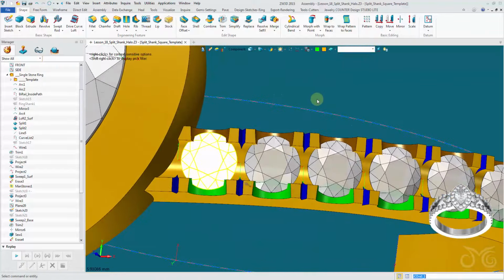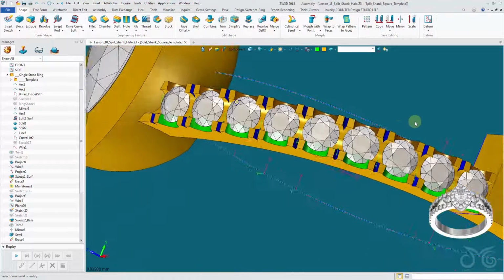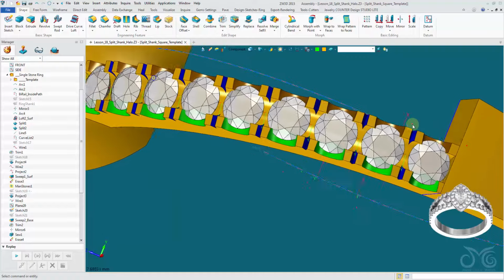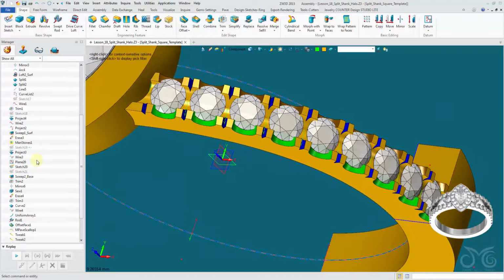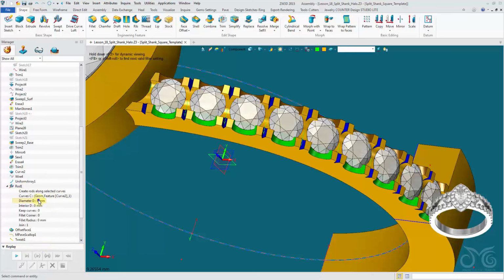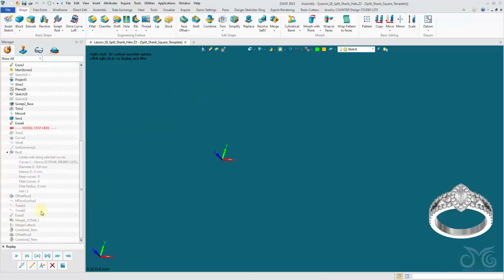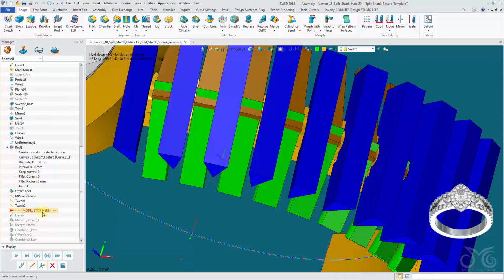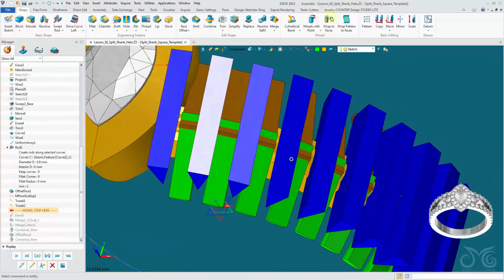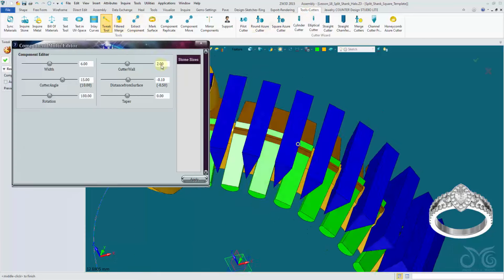Okay, so we don't have much material covering the stone here, so I may want to come in and modify my scallop a bit. First of all, I'm going to open up the rod. I'll drop the diameter of the rod down to a 0.9. We can delay the solve, that's fine. I'm going to come after the tweaks. I'm going to tweak again. Tweak tool.